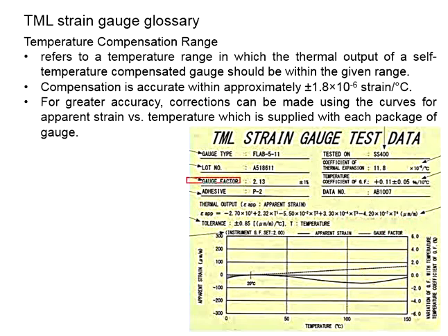Now the gauge factor by default is 2.3 plus minus 1%. This is applicable to 20 degrees Celsius. The temperature coefficients of gauge factor is given here, and it is also referring to 20 degrees Celsius. Let's say now you are measuring a specimen under high temperature. You may refer to the curve here. Based on the factors here, do some corrections to your results.